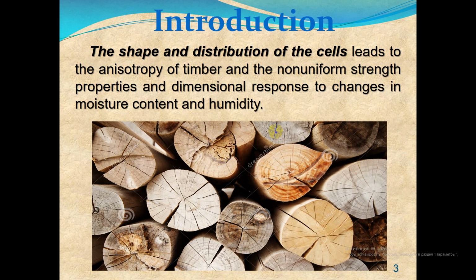The shape and the distribution of the cells leads to the anisotropy of timber and the non-uniform strength properties and dimensional response to changes in moisture content and humidity.